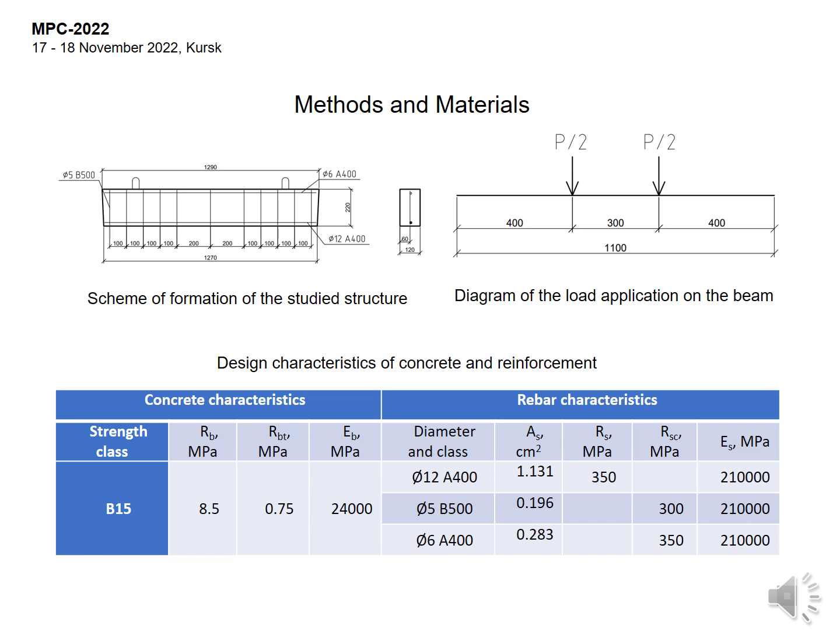Reinforced concrete beams made of heavy concrete of class B15 were selected as control samples. The geometric dimensions of the cross-sections of the prototypes, the classes of concrete and reinforcement, the configuration and diameters of the reinforcement rods were adopted on the basis of preliminary calculations, taking into account the prevention of destruction along inclined sections or due to the loss of overall stability. The reinforcement scheme of the samples is shown in Figure 1.